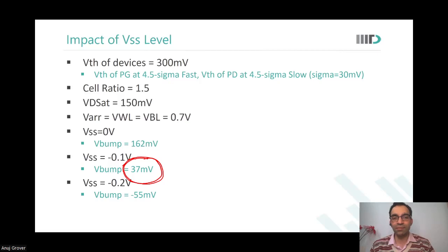So yes, if you have a very controlled VSS, a very small capacitance on the VSS, very small in terms of not femtofarads, but not a huge capacitance, then you can do this. It may be power efficient. If not, then taking the entire memory array in every read cycle to minus 0.2 volts is a huge power consumption, so you may not be able to use the technique.